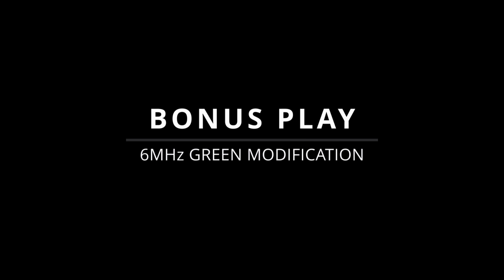So after changing the green input horizontally to the 6 MHz signal, now we have discrete pixels on each line. You can't see it too well in the picture, but on the PVM it's clearly breaking up each pixel horizontally, not a solid line like is shown horizontally in the other colors. It's amazing to see how sensitive the CRT is to tiny time periods that dip to 0 on the 6 MHz waveform.